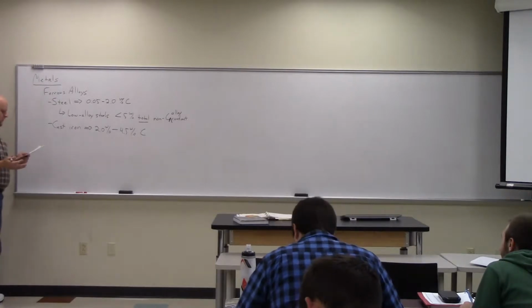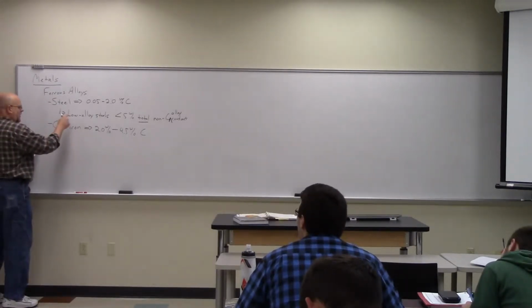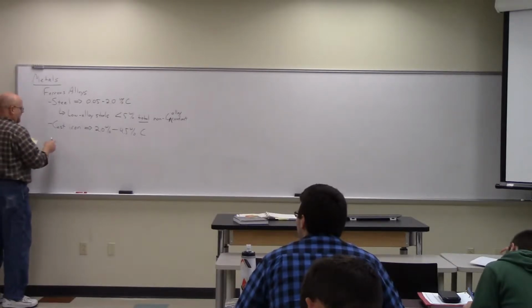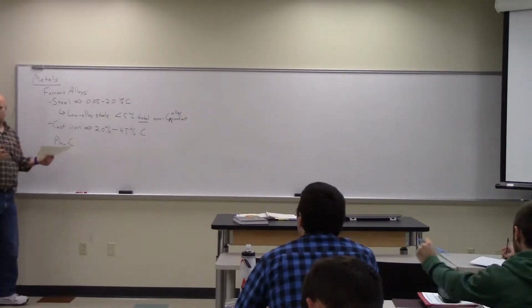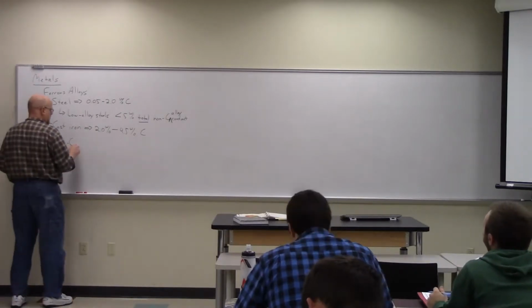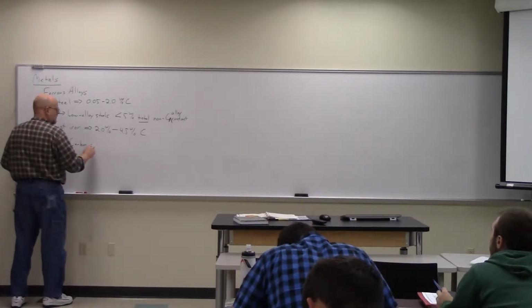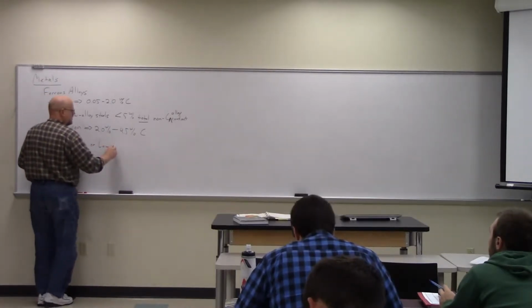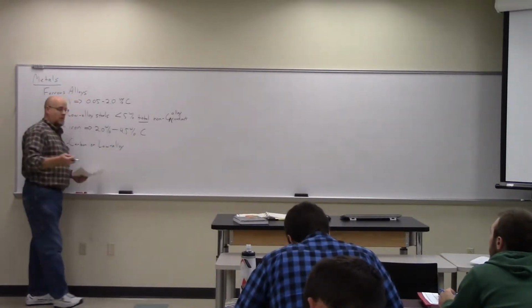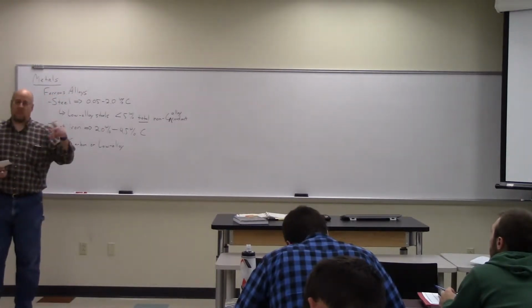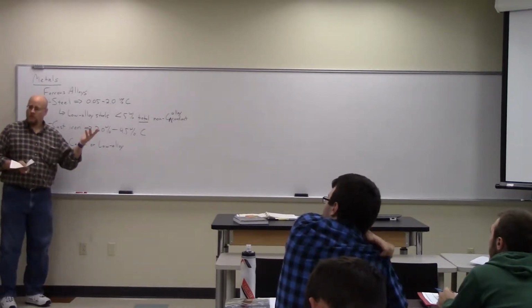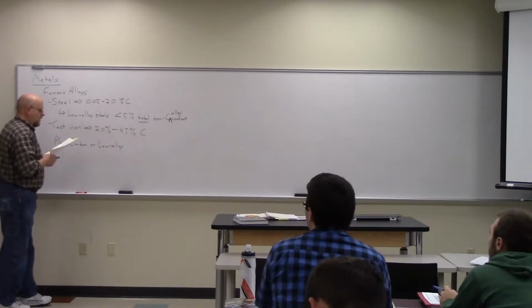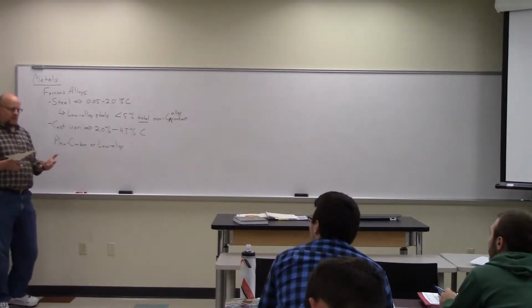So these are the two, ferrous alloys are the biggest chunk. The low alloy steels are the most common. So either the plain carbon steel would obviously be just carbon and iron and nothing else, or the low alloy are the most common because they're least expensive. If I got to keep putting more alloying elements in there, it's going to make it more expensive. The steel is cheap, chromium not so much. Chromium is an element. Cr.